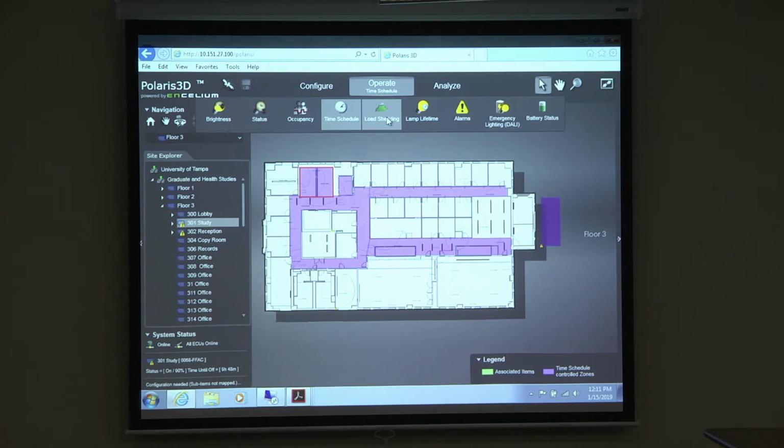Then you set up what we call an overnight calibration, in which the sensors dim the lights and calibrate so they know how much light is coming in, and the fixtures inside will dim accordingly. So in the daytime, if the sun is coming in, the lights inside will dim to maintain 50 foot-candles in that space. In a sense, you're reducing the artificial light output to give you a total output of light in the space. So that's daylight harvesting.